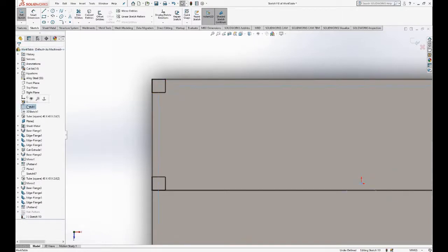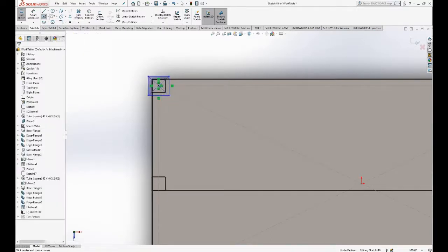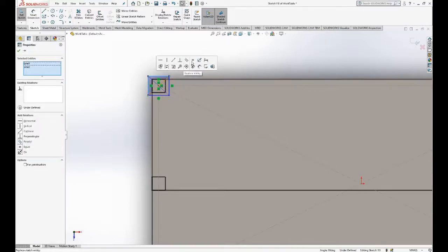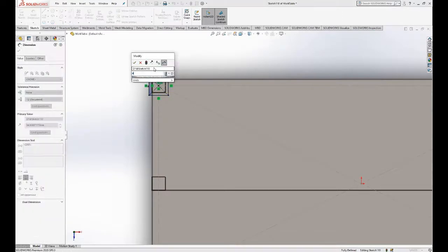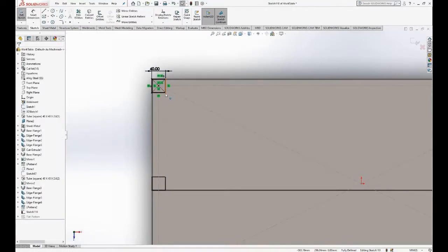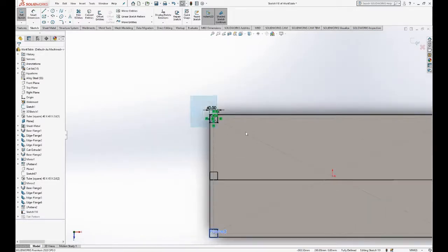So next I'm going to go ahead and open up the universal beam. And we need to capture some of the dimensions that are in here. So I'm going to go to the dimensions and features part here. And you have to pay close attention to how these things are modeled. So what we've done is from this left plane to the right end plane, these are actually the two planes of the center of my uprights. So if I double click on the right end plane, you can see I can control the distance of the planes, which are going to be the centers of the uprights.